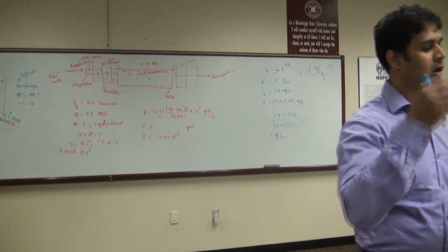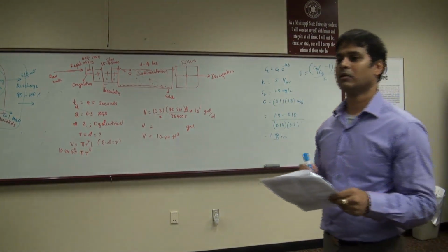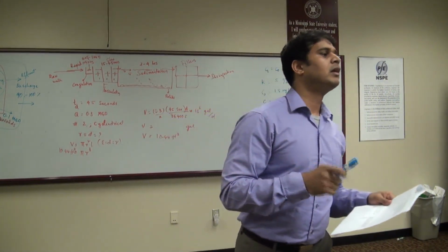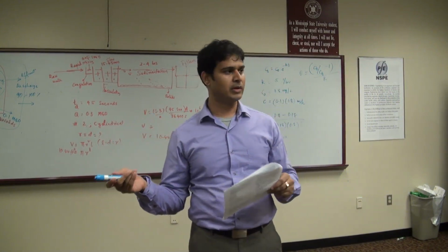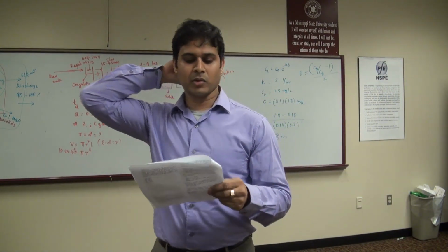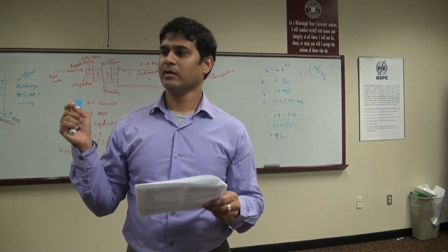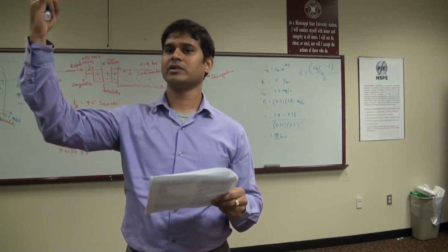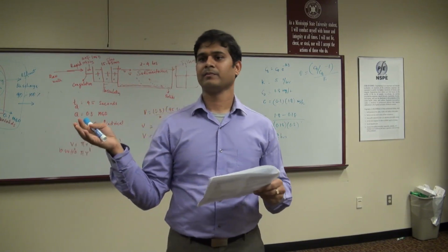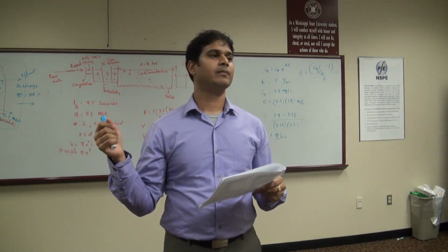But what are the compounds of hardness? The plus 2 ions. That's right. So calcium and magnesium. So you can ignore sodium. Sodium is just given to you. Don't use sodium. So what do we need to do? So divide by the molecular weights for calcium and magnesium, and we need to get them in moles, right? Molecular weights, you're right. So now after that, what do we do?